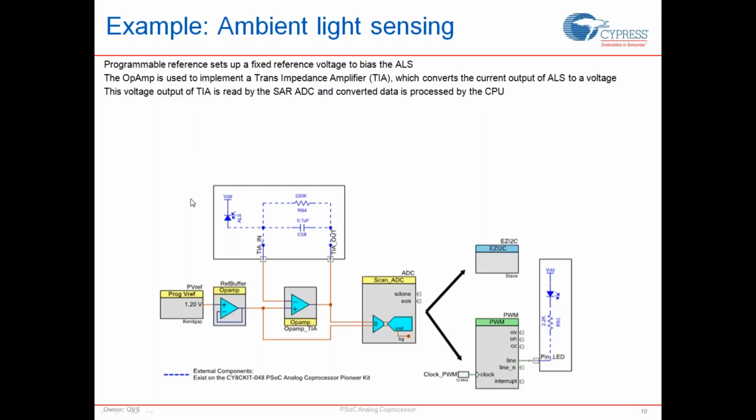That sets up the bias voltage for the sensor, and the sensor now provides a current based on the amount of light that comes in. That current cannot flow into the op-amp, so it flows through the resistor. That drops a voltage across the resistor, hence you see a voltage on the output of the op-amp.